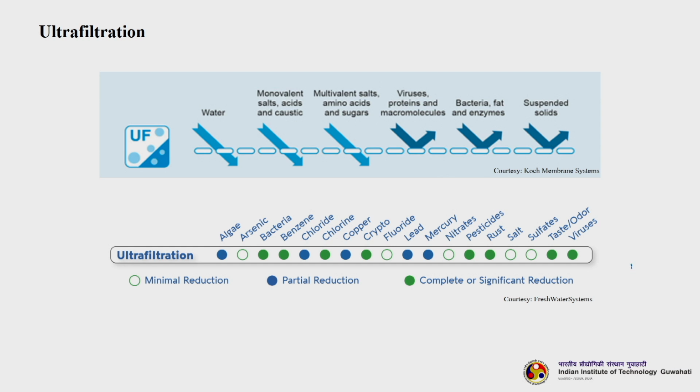So, mostly ultrafiltration membranes are skin membranes. You can consider this as a microporous support, and over that there is a skin layer. It is just like your RO asymmetric membranes, but RO membranes are not actually porous, whereas here the skin layer is also porous. So, that is why you need to understand this.